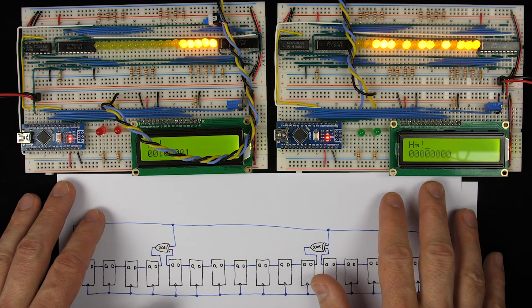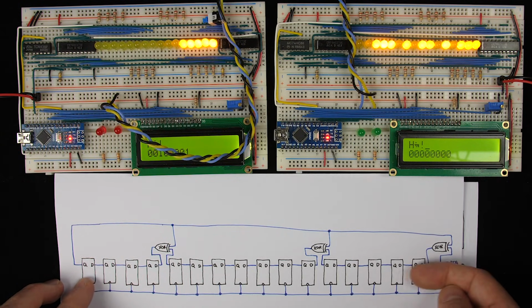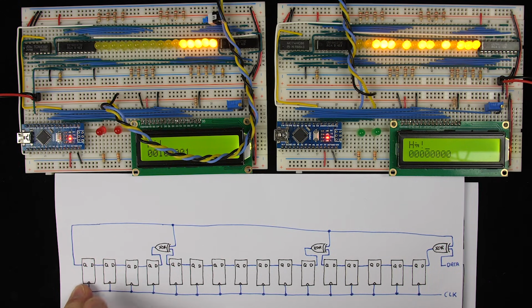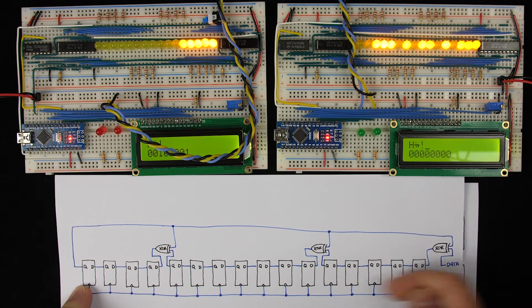However, there is a little bit of a problem with this, which is that once we have a valid CRC in here, we want to be able to shift it out without modifying it. And the way this circuit is set up, we can't really do that because we've added these XOR gates. As it's shifting out, if there's ever a 1 here, then these XOR gates are going to start inverting things, and that's going to mess up our CRC, and we aren't actually going to get the correct CRC out the other end.